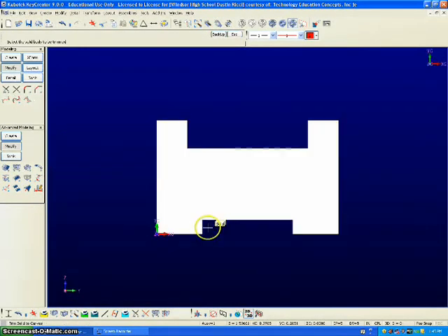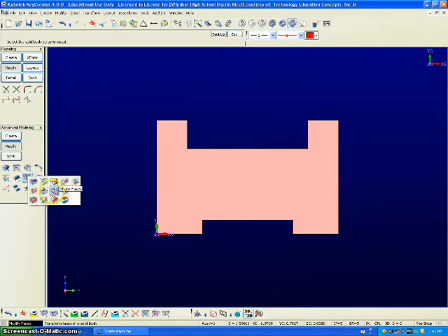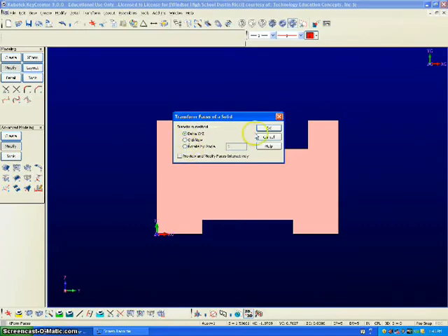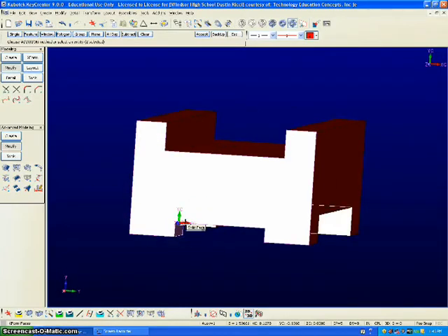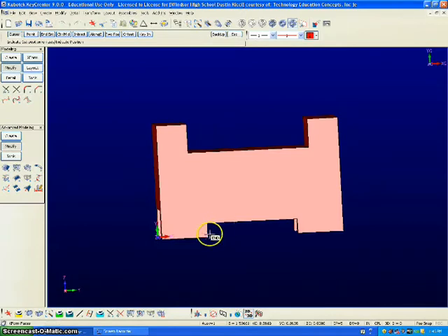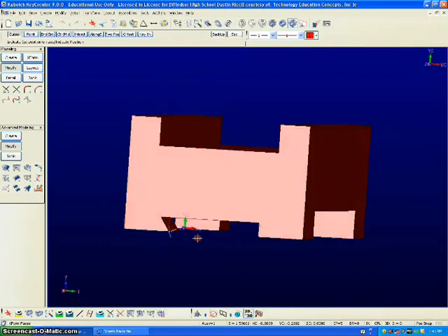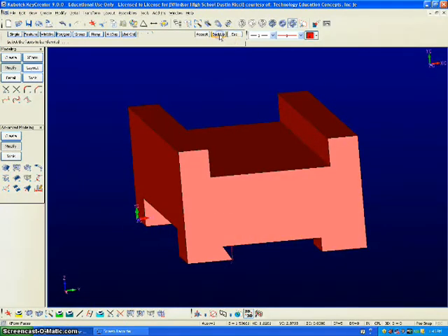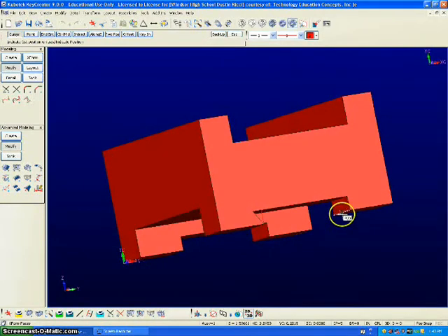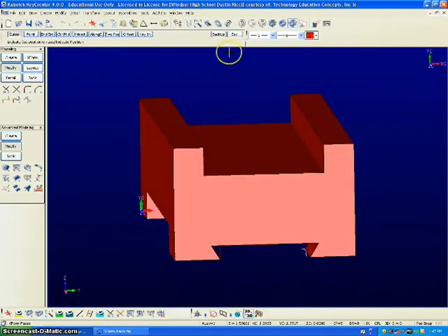So now we're going to modify this side right here. So we're going to go to modify faces, X-form faces right here. We're going to do rotate by angle, 30, OK. Select the face, we're going to do this face. Alright, see what I just did there? So there's now a 30-degree angle on that side, so we're going to do the same thing, except on this side. To the front face and that little side face right under the block, accept. And now that side is done.